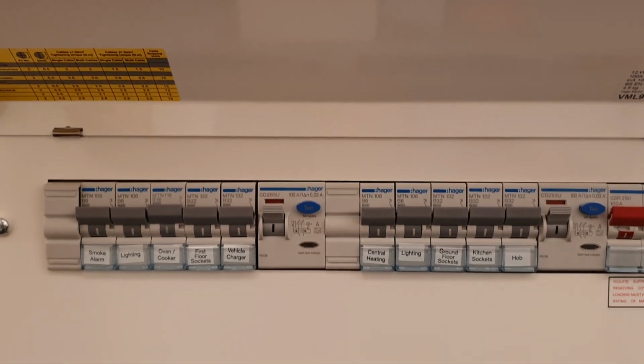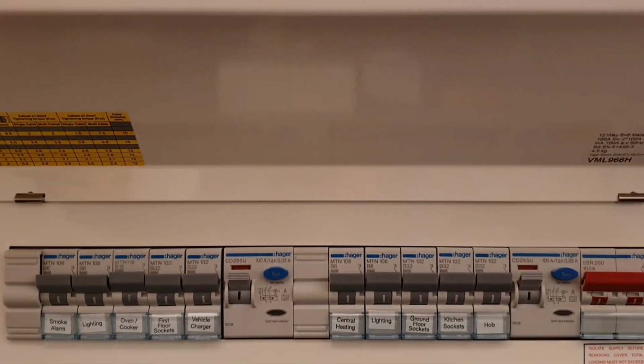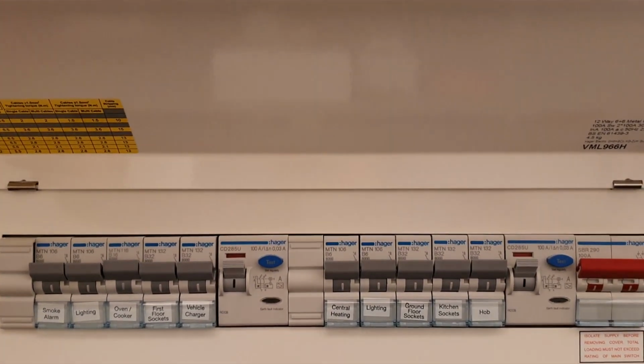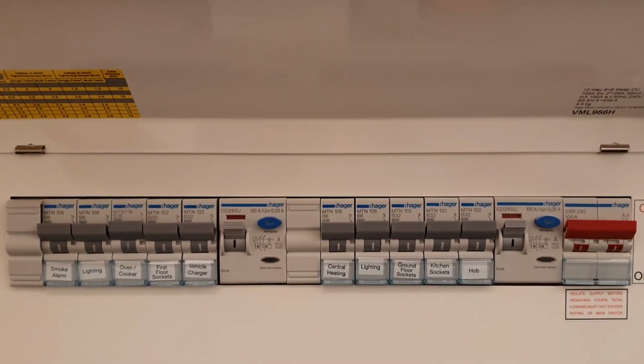But one problem that I noticed with this particular consumer unit is the circuit breaker on the left hand side of the image that says smoke alarms also does the lighting. Now I think what's probably happened here is maybe the contractor ran out of labels, but also there's not enough space to put the label for both. So this is why I think that it's really important to have circuit charts for consumer units that accurately reflect what the circuit breaker protects, so that it's possible for the end user and any other electricians that may work on the property afterwards to safely identify the circuit.